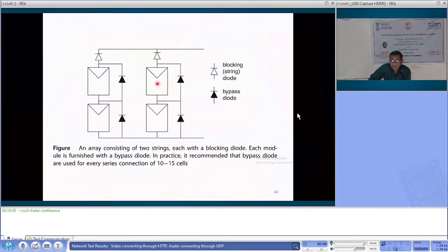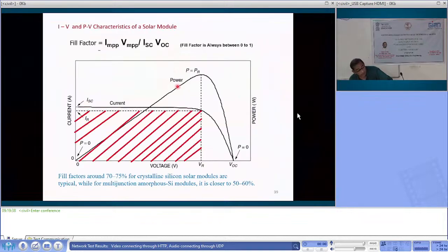So I guided one MTech student and he presented a paper at NIT Bhopal, this student conference, on the partial shading conditions of the PV module, and he considered several cases and then simulated like this. तो ये blocking diode जो दिखाया है, ये dark वाला नहीं, दूसरा, that has to block, because if you are connecting through a converter to charge a battery, you don't want reverse current, उसको block करना है, इसका नाम blocking रख दिया. Bypass means the solar panel is shaded, then you should have diversion, so bypass route is there. So that is the basic concept and their functions are important.